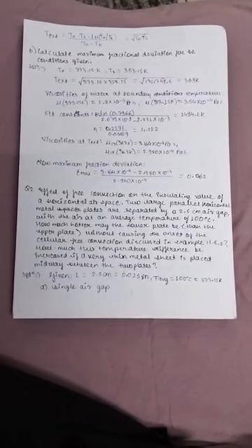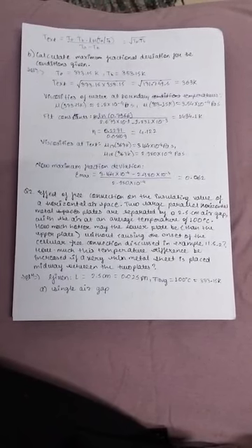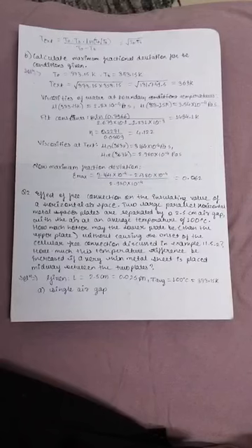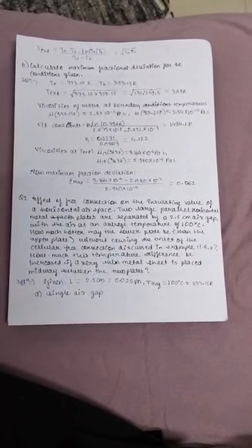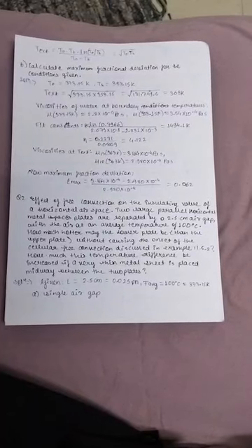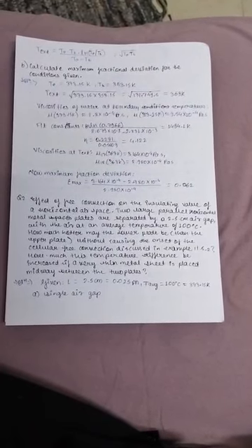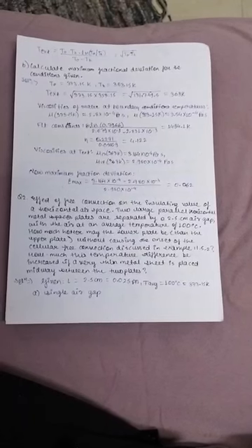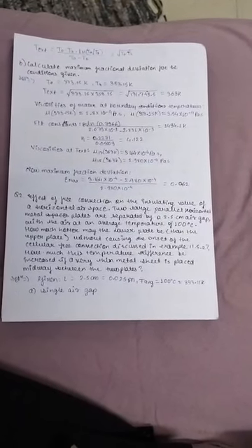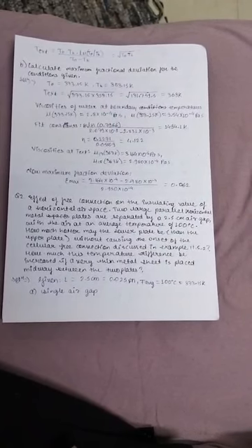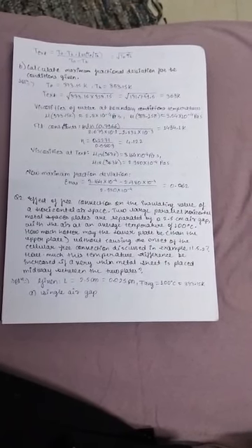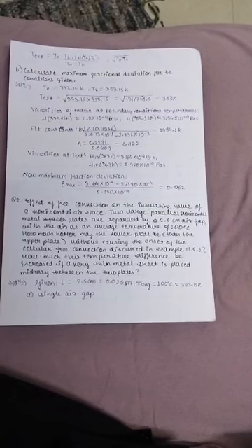Fit constants: B equals ln of 0.7966 divided by 2.679 times 10 to the minus 3 minus 2.831 times 10 to the minus 3 equals 1494.1 Kelvin. N equals 0.2271 divided by 0.05509 equals 4.122. Viscosities at T max: mu 17 at 363 Kelvin equals 3.164 times 10 to the minus 4 Pascal seconds. Mu 18 at 363 Kelvin equals 2.980 times 10 to the minus 4 Pascal seconds.